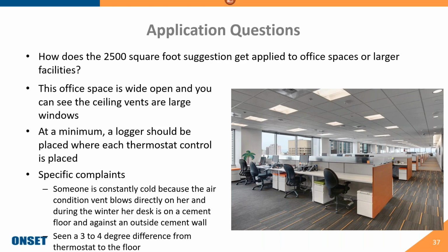We've had an instance at our own building where a particular employee had the vent blowing directly on her, and she was also against a cement wall, which has a lot of cold that comes through it during the winter. So we were actually able to see a 3 to 4 degree difference from the thermostat to where her feet were.